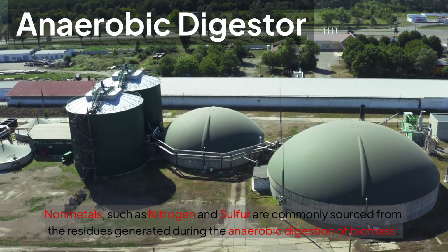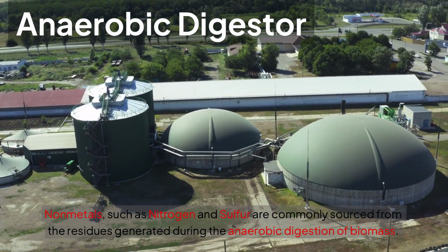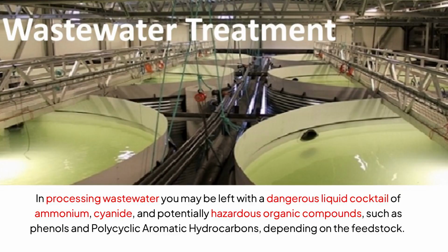Nonmetals, such as nitrogen and sulfur, are commonly sourced from the residues generated during the anaerobic digestion of biomass. They migrate into the gas and biooil fractions, generating toxic gases like ammonia, NH3, hydrogen cyanide, HCN, and hydrogen sulfide, H2S. In processing wastewater, you may be left with a dangerous liquid cocktail of ammonium, cyanide, and potentially hazardous organic compounds, such as phenols and polycyclic aromatic hydrocarbons, depending on the feedstock.